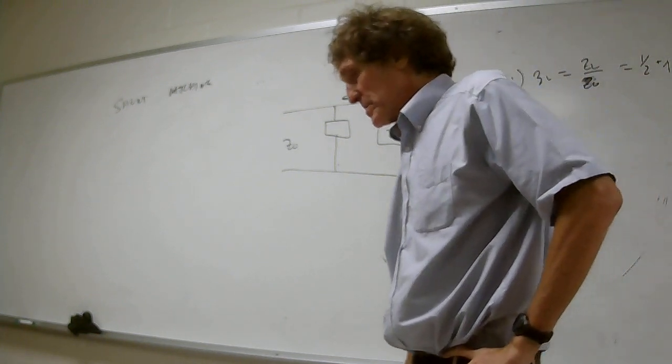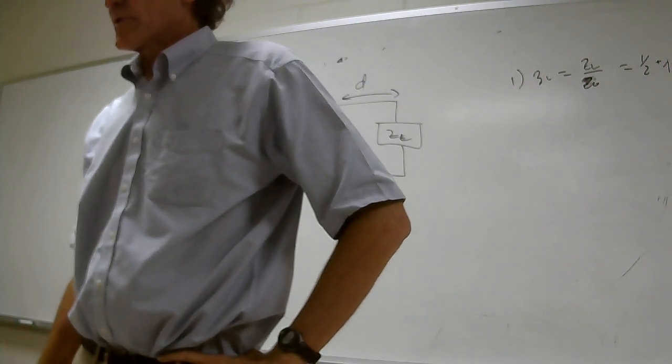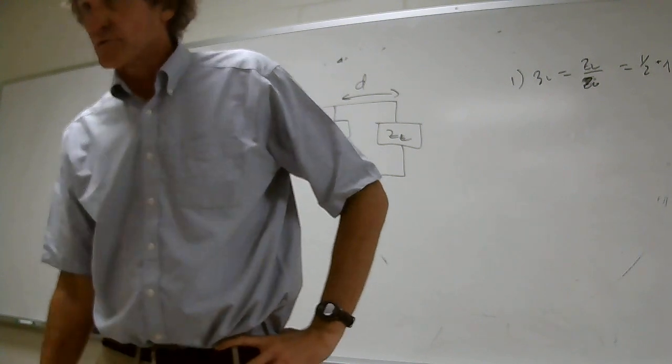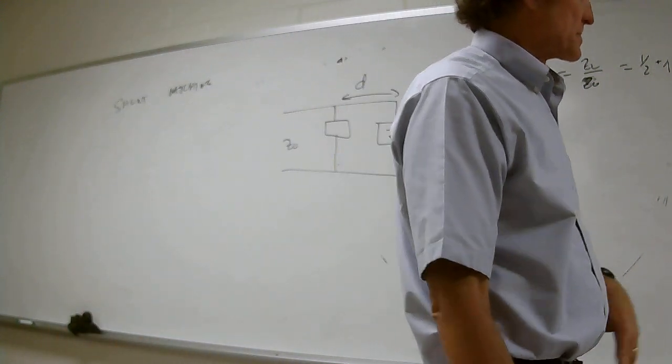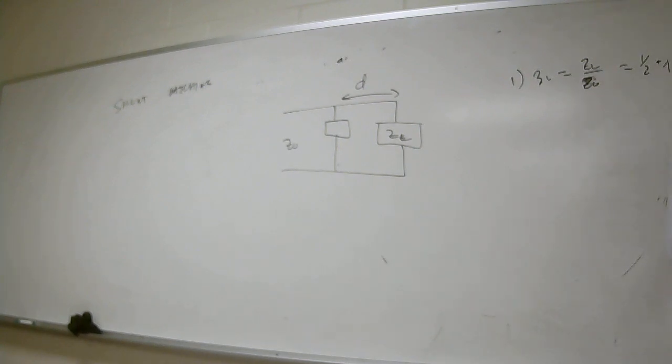I want you to see this clearly. The reason is that we're going to very easily get the value of the admittance, which is 1 over ZL, the normalized admittance. Now, this is ZL. Take your compass and draw a circle of this radius, constant reflection coefficient, and you draw a circle that big, something like this.